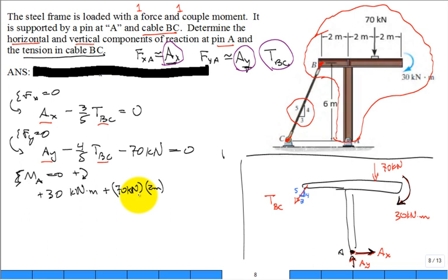All right. Now, what about this tension B to C? You could do it in 2 ways at least. You can decompose it into 2 parts. One would be the tension B to C, and I would pick off the 3/5, right? That's the horizontal component.